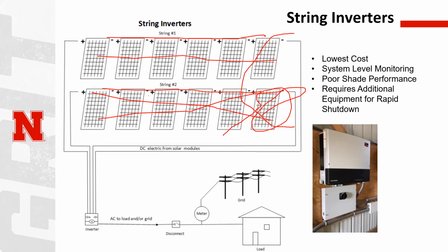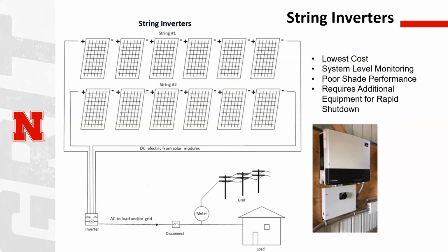So shade is bad for solar. Now, this is a really high level academic idea. Shade is bad for solar, but it's extra bad for string inverter solar, because when I have a little bit of shade, I lose everything in line with that string. It's kind of like that flashlight battery example where I take the batteries out. I've got four dead batteries, but I only have 3 new ones.